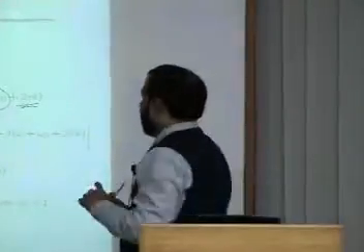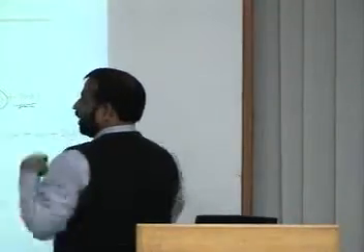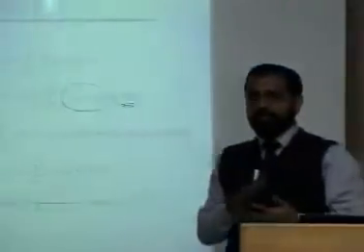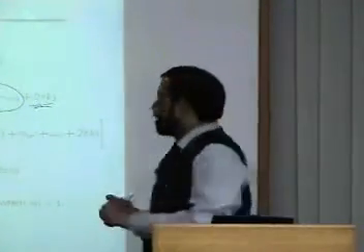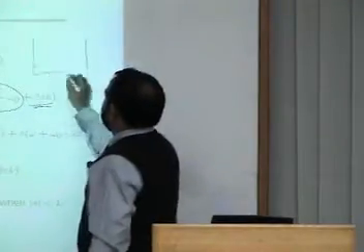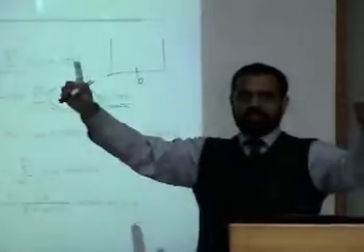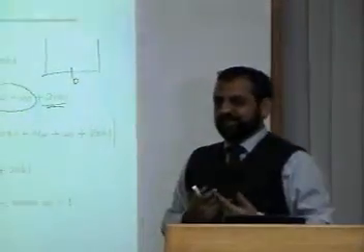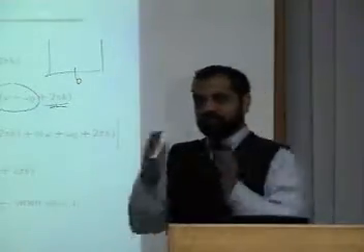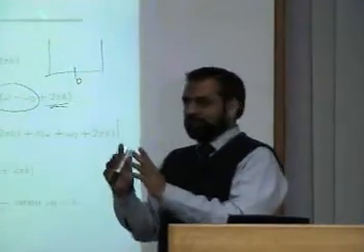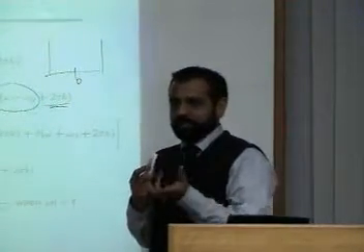If you find two of these, one on this side and another on this side, you can rephrase the sentence and say how many cosines are there, because a point here and a point here means the cosines are there. If a signal is real, its Fourier transform for sure is going to have a point here and a point there. It means that there will be cosines in a real signal.